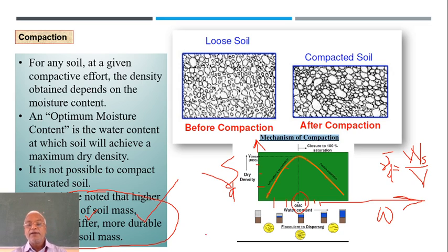Okay, here in the picture also you can just see there is a dry soil and a lot of volume of air is there. I don't know whether you are able to see that. Here there are soil particles which are kept the same, weight of solids kept the same. Here this white space is air voids, and you add a little bit of water and volume decreases.